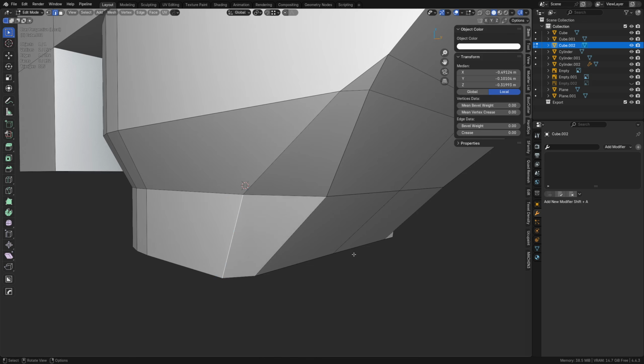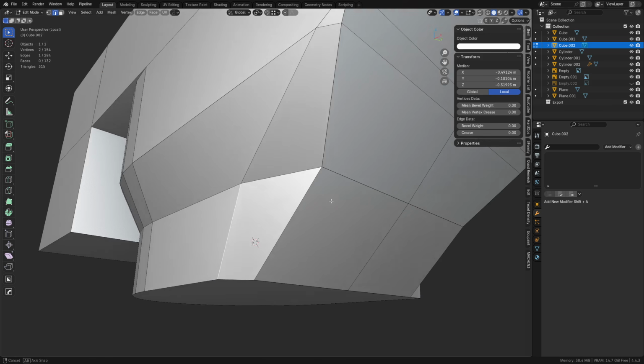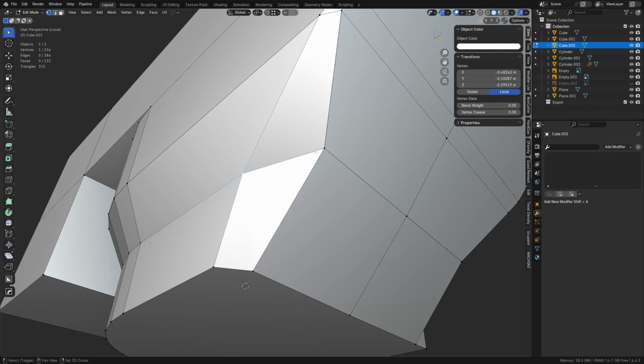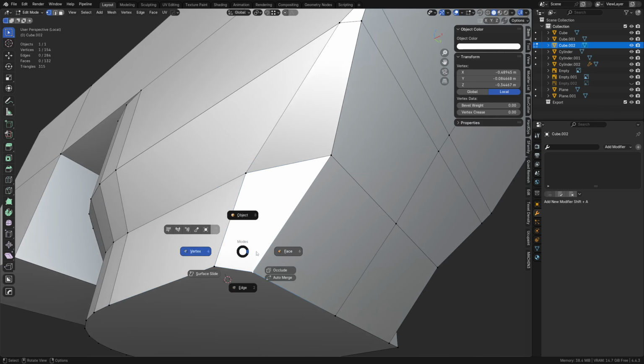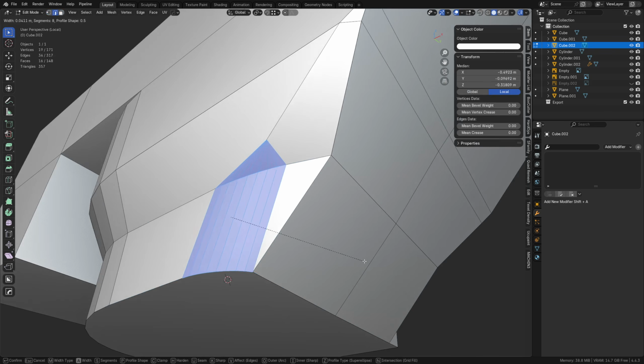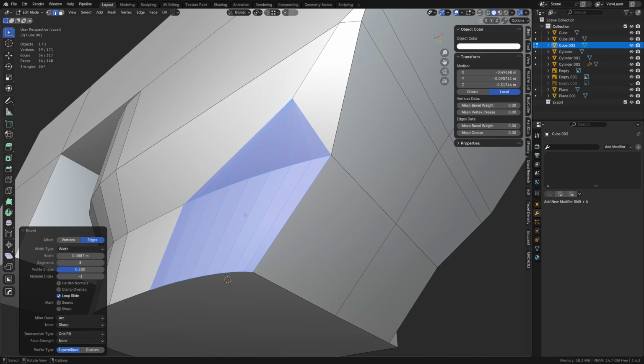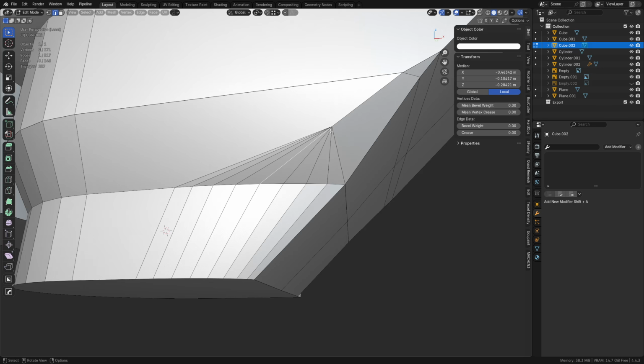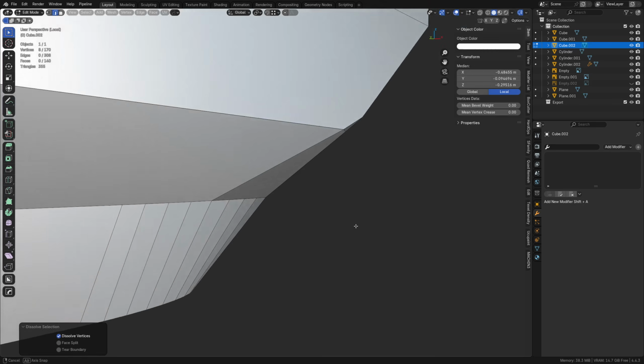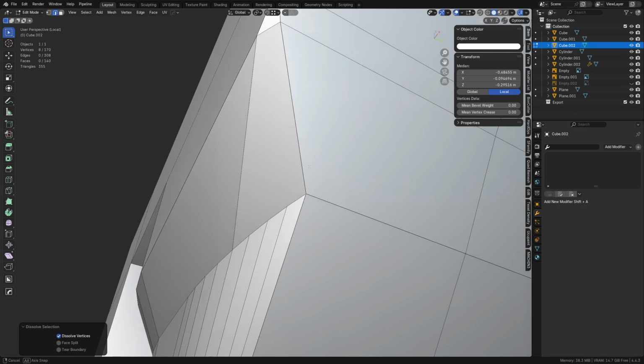I need to change this back to offset until they fix that bug. I can't stand Blender making bugs all the time. I don't usually clamp, but sometimes I do need to, and you can see this just works better. Kind of doing something like that. And if we dissolve the right edges here, it might actually work out really well this way. You see? Boom.